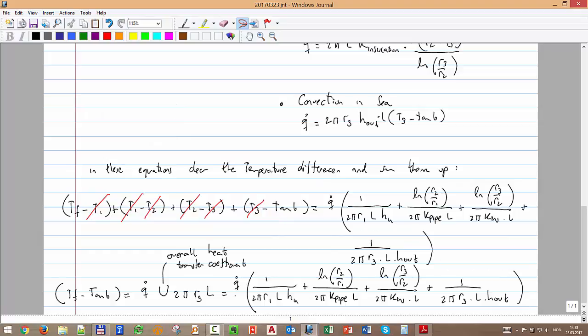Okay, then you will see, you can take... sorry, the area should be down, okay? Because we want to make it... sorry, that was a mistake. Just like with convection, you have Q equal to an area times a coefficient times a delta T. We want it to look like that, so then delta T equals Q over A times h.